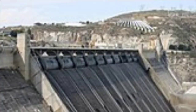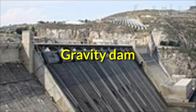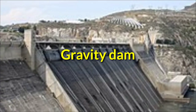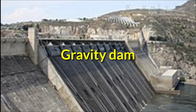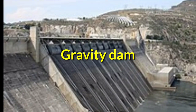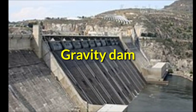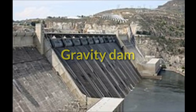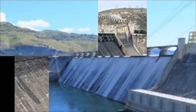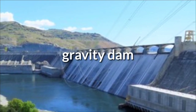The next dam in this category is the gravity dam. A gravity dam is a structure designed to withstand loads by its own weight and by its resistance to sliding or overturning on its foundations. Newer dams of this type are typically composed of unreinforced concrete or monoliths with seals at the joints. But in past centuries, many gravity dams were usually constructed of stone masonry.